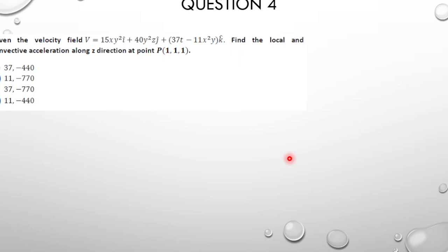If you take the momentum equation, the rate of change of momentum is attributed to two factors. One is the change in momentum happening inside a control volume. If we say finite volume method, then we come across control volume. So momentum which is increasing inside a control volume, from within the control volume, that is the local part.